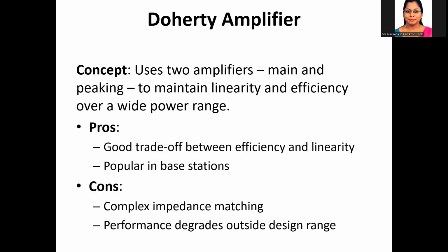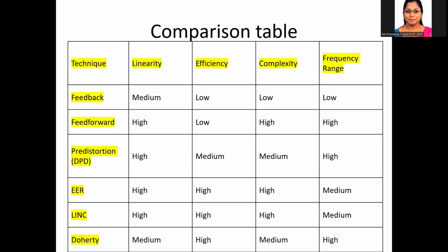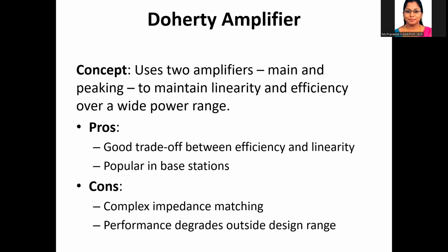The concept is two amplifiers. What are they? Main amplifier and peaking amplifier. The main amplifier will operate continuously at low and medium power levels. But the peaking amplifier is turned on only when the higher output power is required. Applications: we are using it in satellite communication systems.